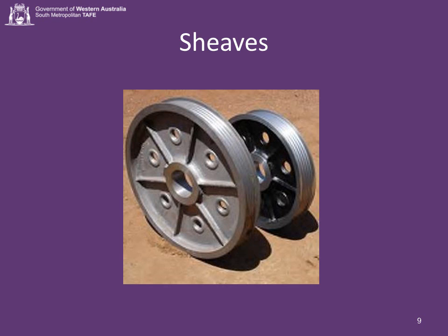For drives where the belt enters the sheaves at an angle, deep groove sheaves are available. These are especially useful when the belts must turn or twist. Deep groove sheaves can be used anywhere belt stability is a problem.